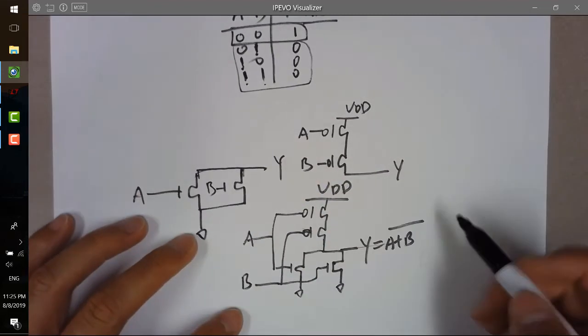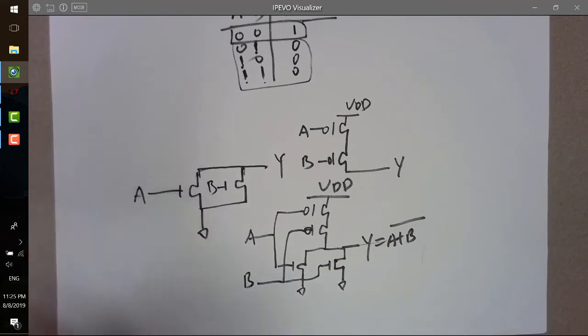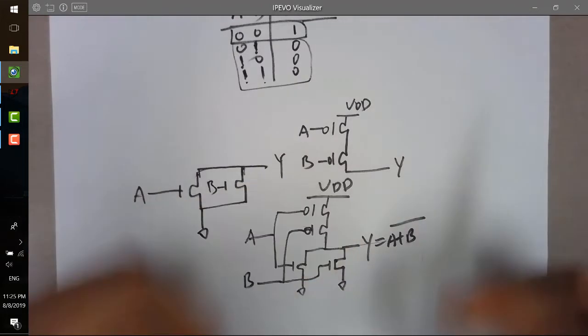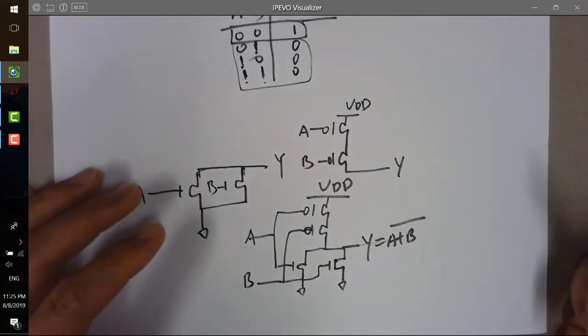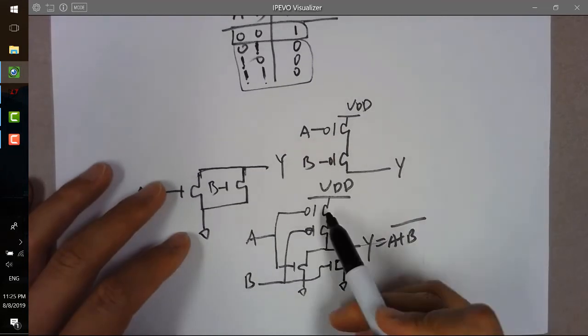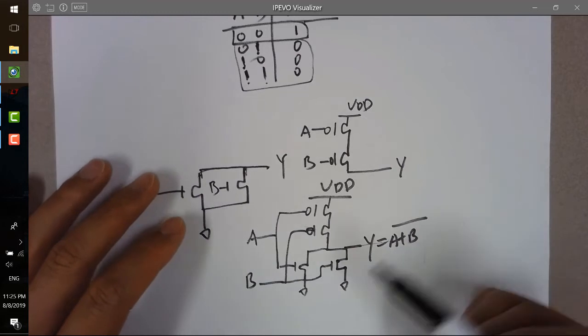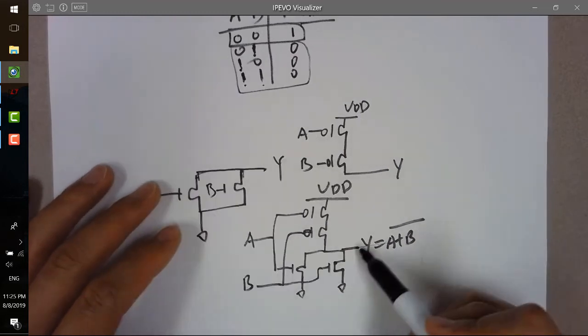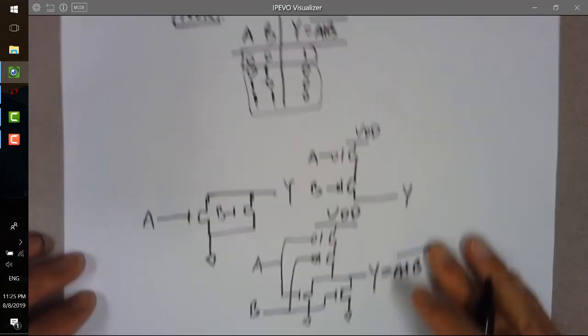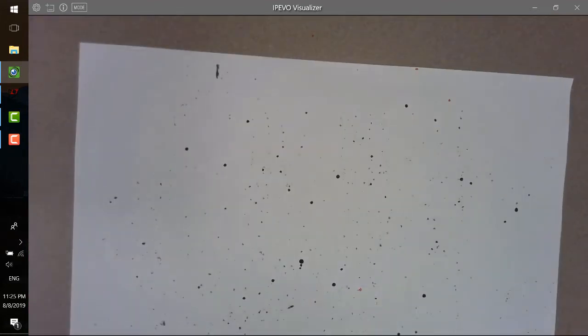If you want to invert it, you invert it outside, because the symbol does not actually exist in a real IC chip, but the transistors do. Usually in the schematic design, we do not directly draw an inverter here. Now let me show you how, so you understand why. It's something you want to know before you go to the simulation.